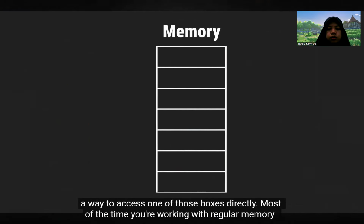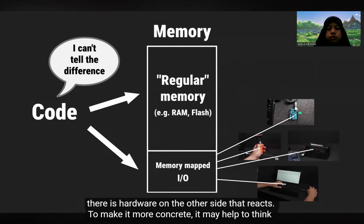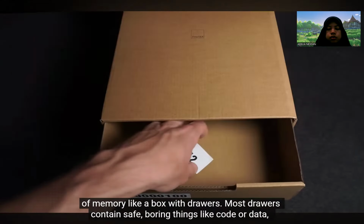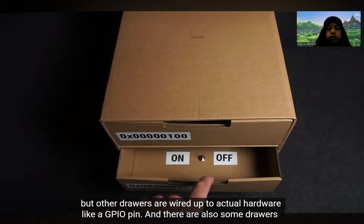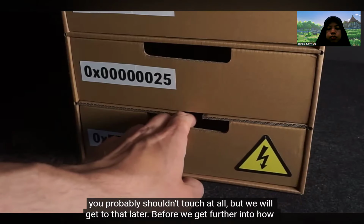Most of the time, you're working with regular memory like RAM or flash, but some of those boxes are wired up to hardware instead. That's what we call memory mapped IO. On the surface, they look like regular memory too, but when you write to them, there is hardware on the other side that reacts. To make it more concrete, it may help to think of memory like a box with drawers. Most drawers contain safe, boring things like code or data, but other drawers are wired up to actual hardware. And there are also some drawers you probably shouldn't touch at all, but we will get to that later.